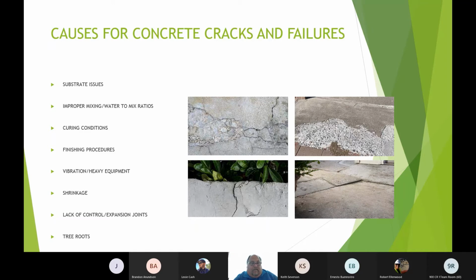That's what you're going to see in a lot of places that didn't have the proper substrate, or they've allowed water to get through those. I think they're expansion joints. It looks kind of like somebody put a puzzle together, but the water got down in there and could have washed the substrate out. There could just be a creek flowing underneath that thing of water draining from another location. So when you have areas like that, you got to look at that.